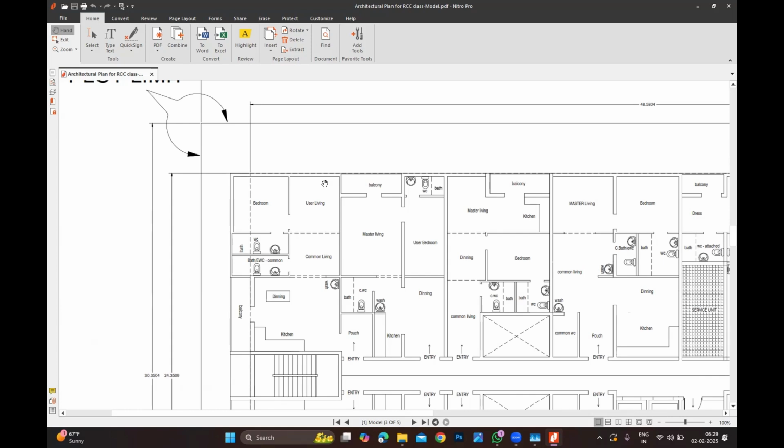When you're increasing from one grade to another grade, it automatically shoots up directly by like 20% of your compression capacity. Correct? If my column is failing, what people used to do is suddenly go and increase the column size. You need to understand under which case the column is failing, first of all. Which combination. Apart from that, either the column is failing under shear or flexure, that is most important. This is the concept.